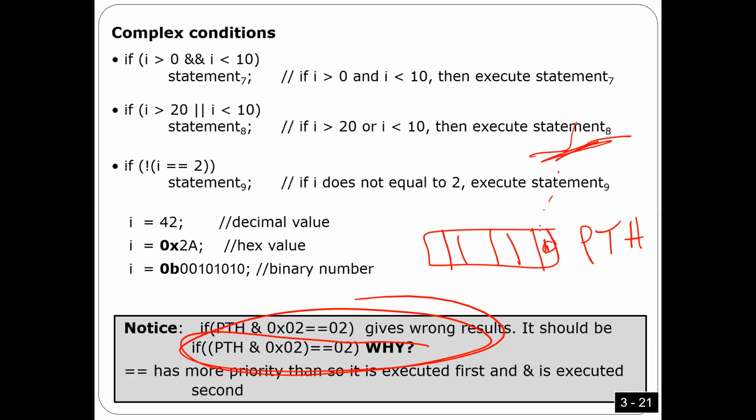So all you have to do is take a byte and check the bits. You need to check 1 bit or more, whatever you want, to see if they are 0 or 1 to know if the switch is connected or not. After that you can decide what you want to do. If the switch is open, what do you want to do? If it is closed, what do you want to do? We're going to do this one later when I explain port H.